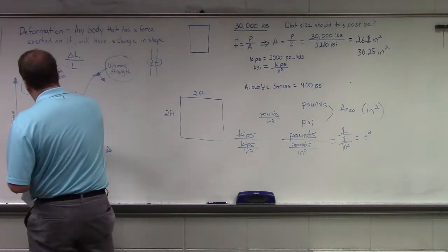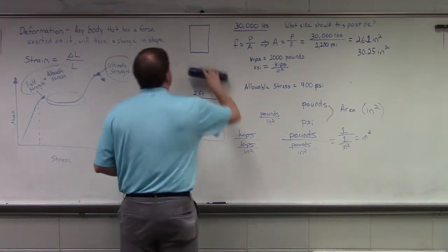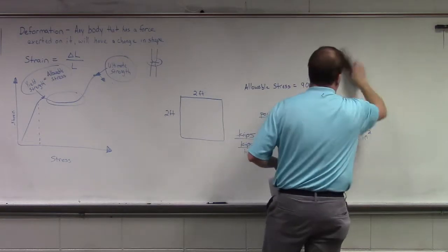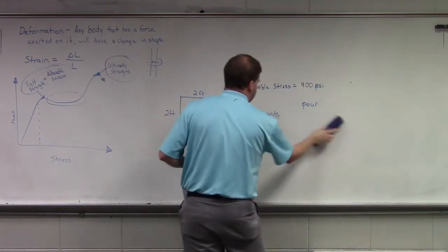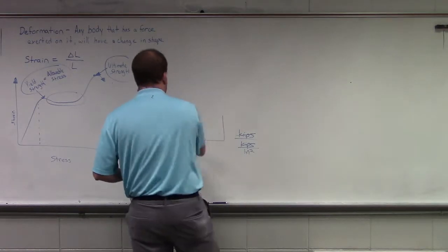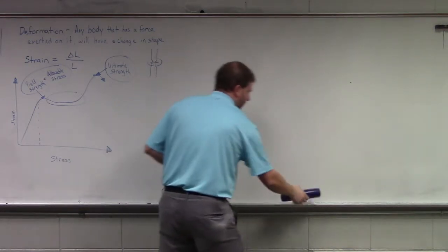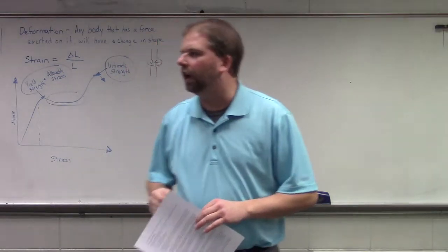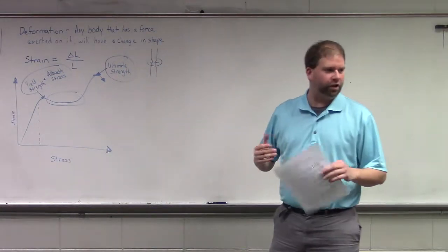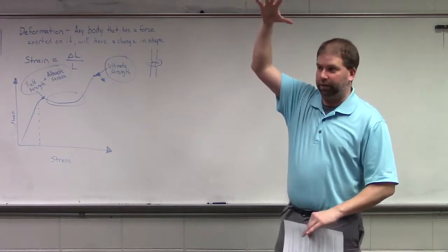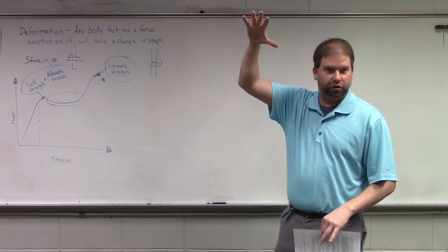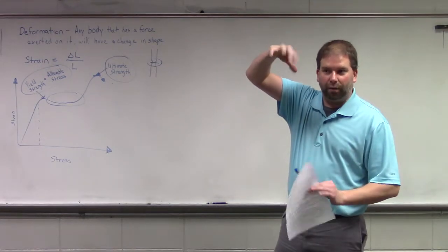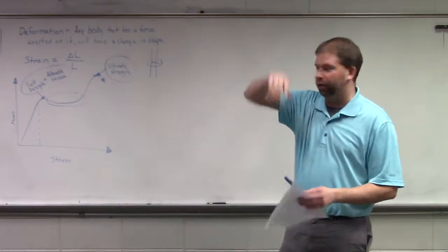Within our elastic area, though, we can determine a material's stiffness. How much does it resist bending? Modulus of elasticity is somewhat important to us for timber, less so than it is for steel and concrete. As with steel and concrete, we're typically building much more massive structures, so we need to know what that stiffness is. How much are these members going to flex as we're loading them?